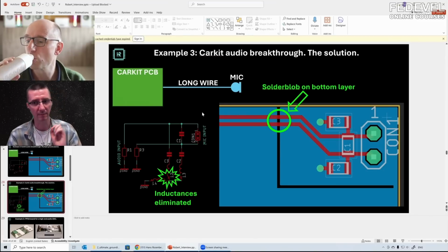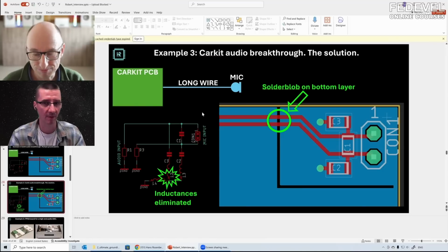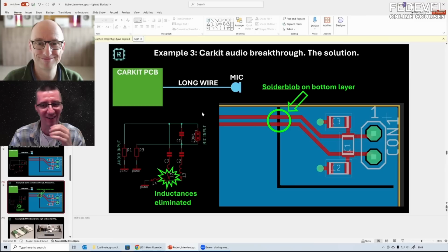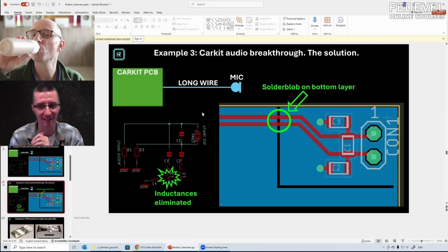Okay, I'm going to add my own experience with this. I have 2. So the first one was very similar to this one. We had EMC problems, but it was at the time when I was very young and I was reading all these data sheets which were saying you have to split grounds. So I created analog ground for the audio part and digital ground for the digital part.